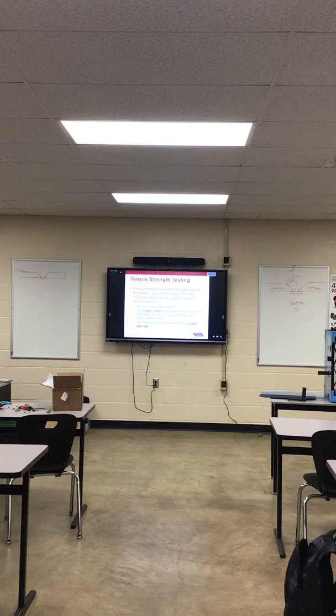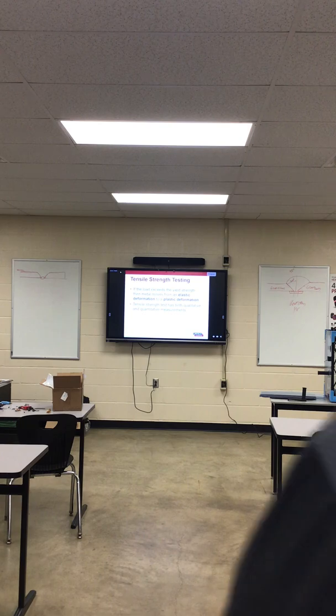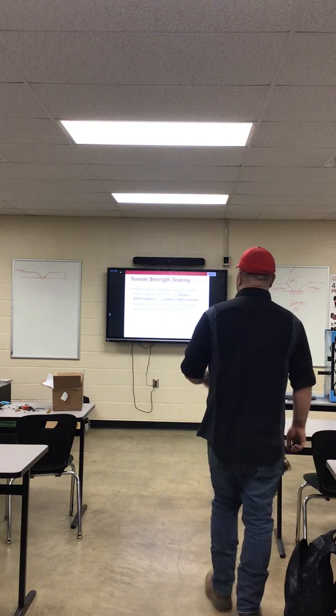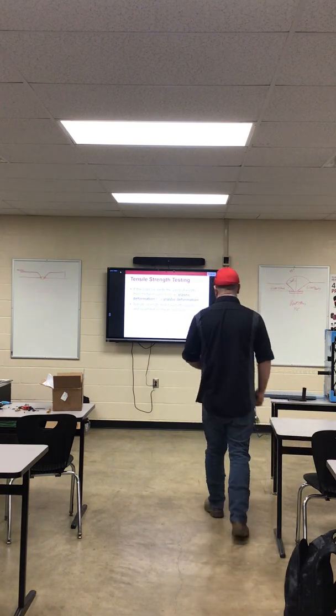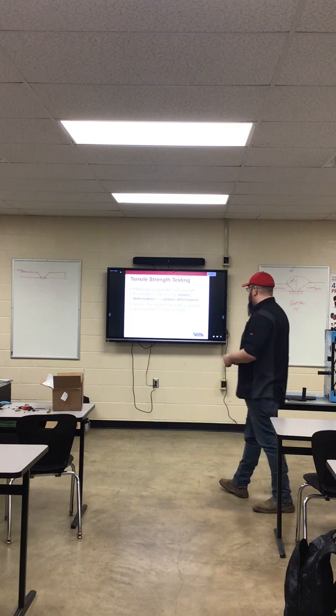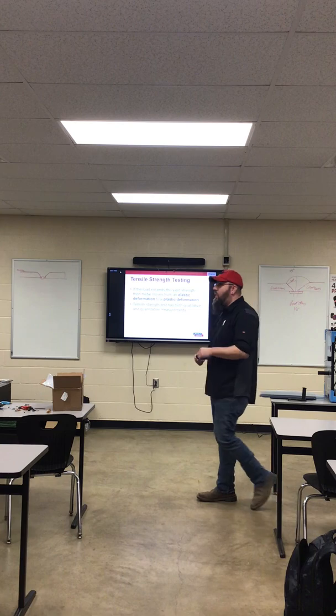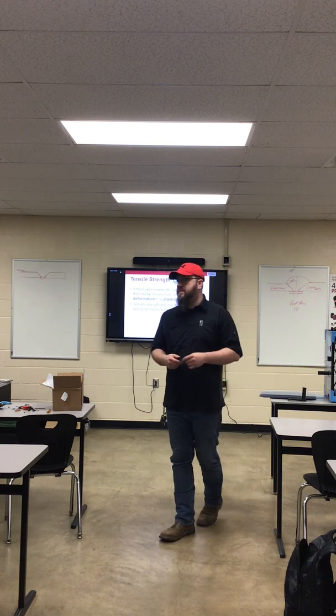The transition point is referred to as yield strength. No, it doesn't mean yield for oncoming traffic. It is yield strength. How much strength or how much effort is yielded in this part. If the load exceeds the yield strength, then metal moves from an elastic deformation to a plastic deformation. Tensile strength test has both qualitative and quantitative measurements.